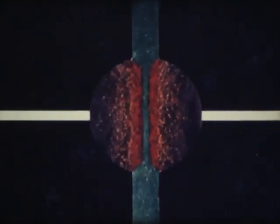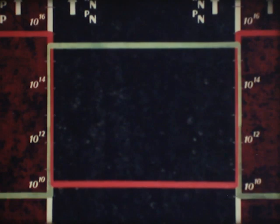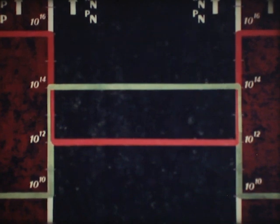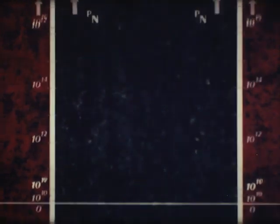So far, we have only considered a PNP crystal, whose three regions contain equal impurity concentrations, shown here on a logarithmic scale. If we now consider a crystal in which the number of foreign atoms in the base is reduced, then the electron concentration in the base region will also be reduced, and consequently, the hole concentration increased. This means that the hole concentration in the base is considerably higher than the electron concentrations in the emitter and collector regions. As we are again considering only minority concentrations, we will return to a linear scale.